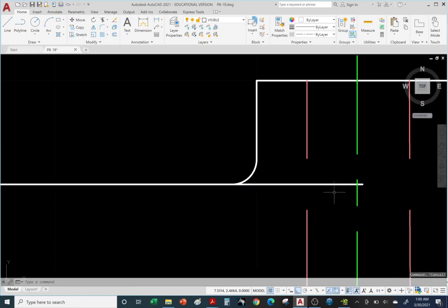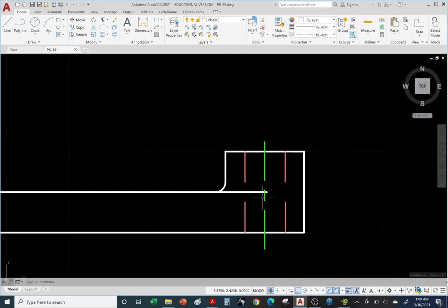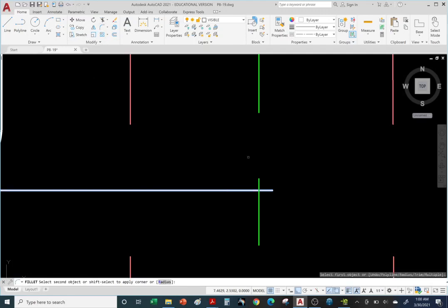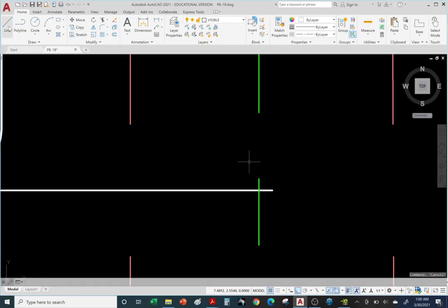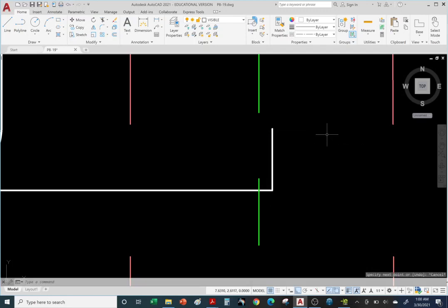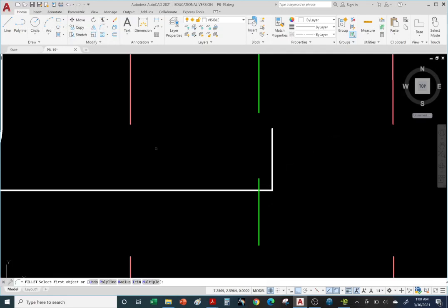And then you can add the next fillet. Let's see if we can do it on this one. Couldn't do it on the other side, but let's see if we can do it here. Go from this one to, oh, it's not accepting it. Let me hit escape. I'm going to try and trick it into creating a fillet. One way is to draw another line at the end point, go straight up, and now we can draw our fillet. This line too. Oops, still not accepting it.